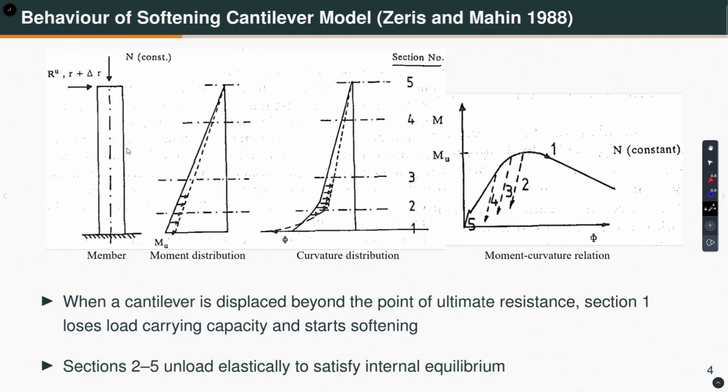As you know, this is a statically determinate structure. So, there is no load in between, meaning that within the element there is no other load, only at this node there is a load in the horizontal and vertical directions. So, the bending moment diagram will vary linearly as shown. This is the moment distribution.